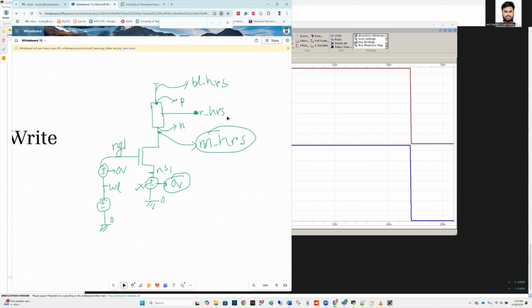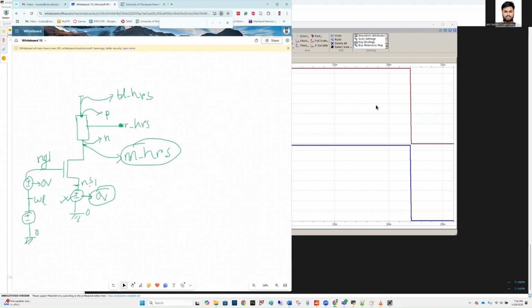It's actually confusing, but that's it, because in a wave view we can only plot voltages. Although the wave view will show this as voltage, the number we are getting from this third pin will actually be the resistance value. So this is a trick to observe values other than voltages or currents.